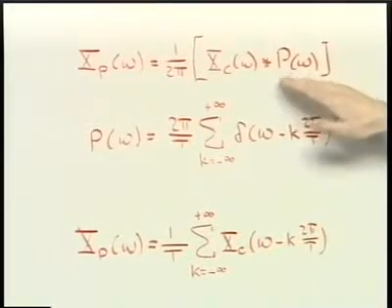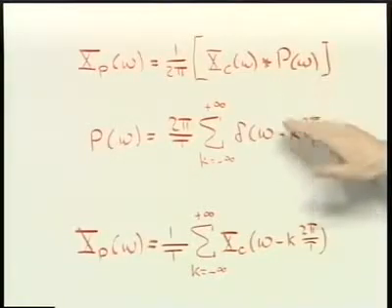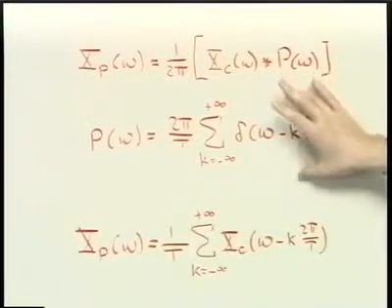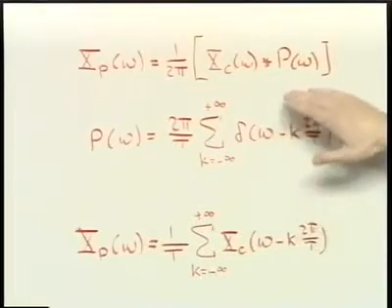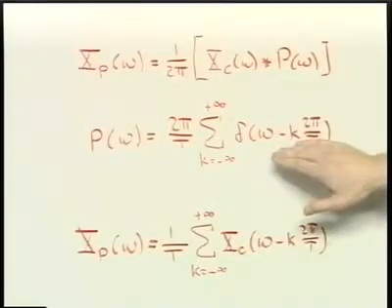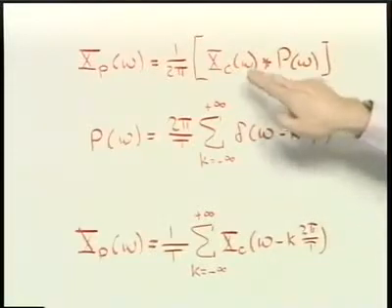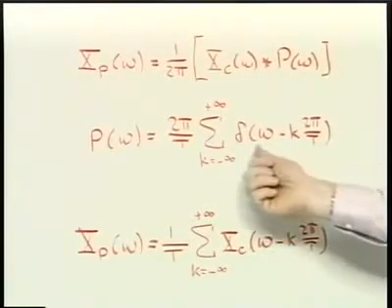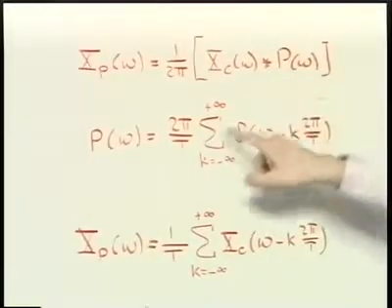Since the sampling signal is a periodic impulse train, its Fourier transform is an impulse train, and consequently carrying out this convolution in effect says that this Fourier transform simply gets replicated at each of the locations of these impulses.